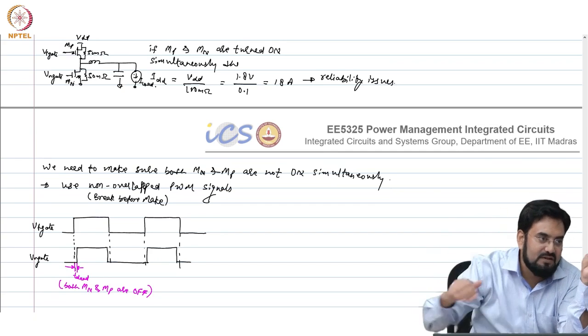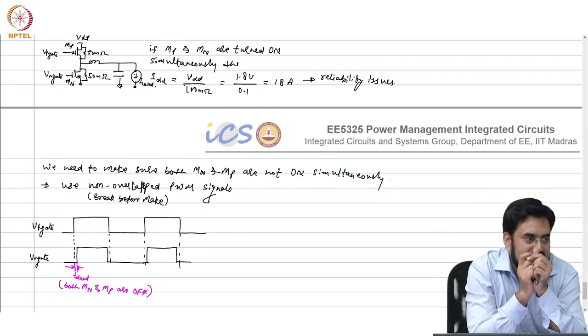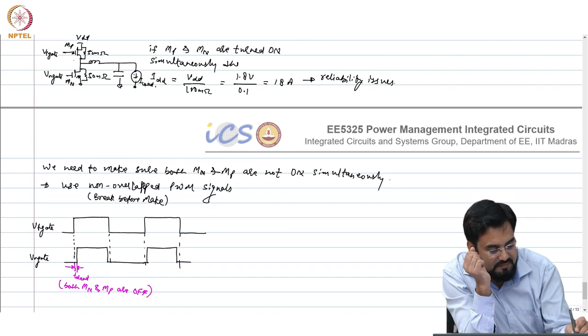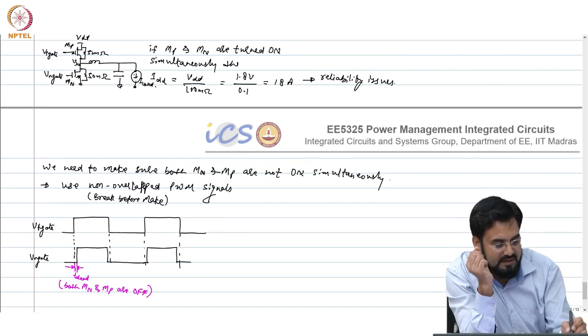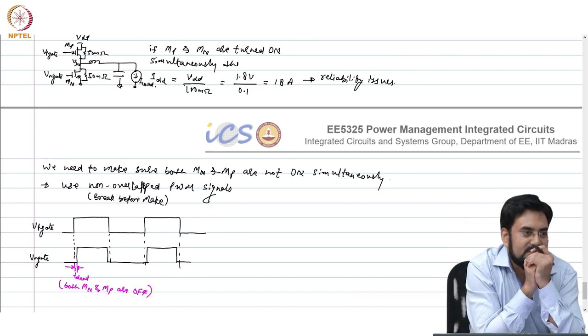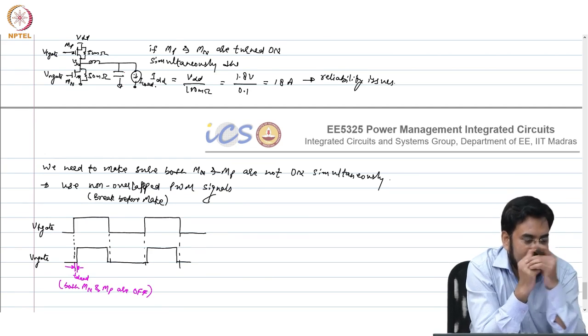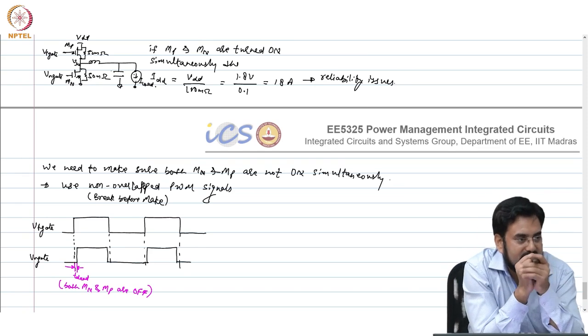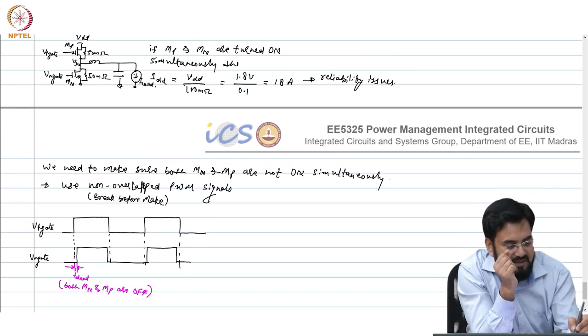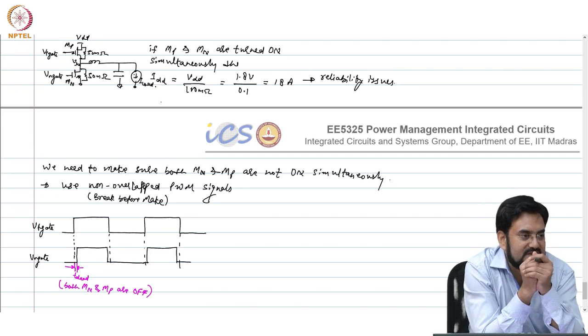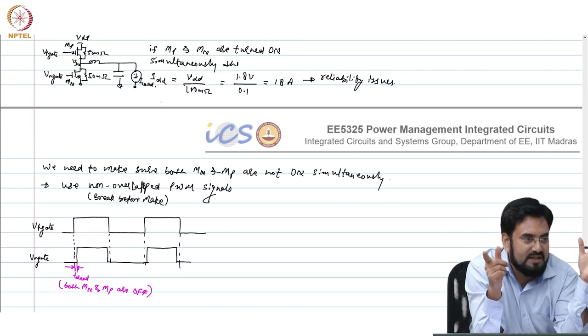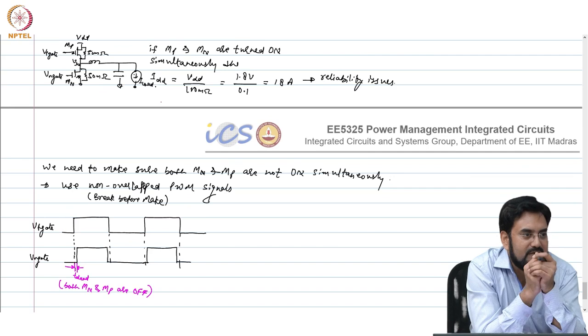So it will rise and fall based on the voltage. So if you leave that high impedance, the other node, if I call it VSW, and the current is still flowing into this. I mean, load current is, let's say, 1 amp. Okay, that was flowing through NMOS, and you turned it off. You leave it high Z. That 1 amp will keep flowing for a certain time, unless the voltage across the inductor falls to zero. Current cannot be zero.